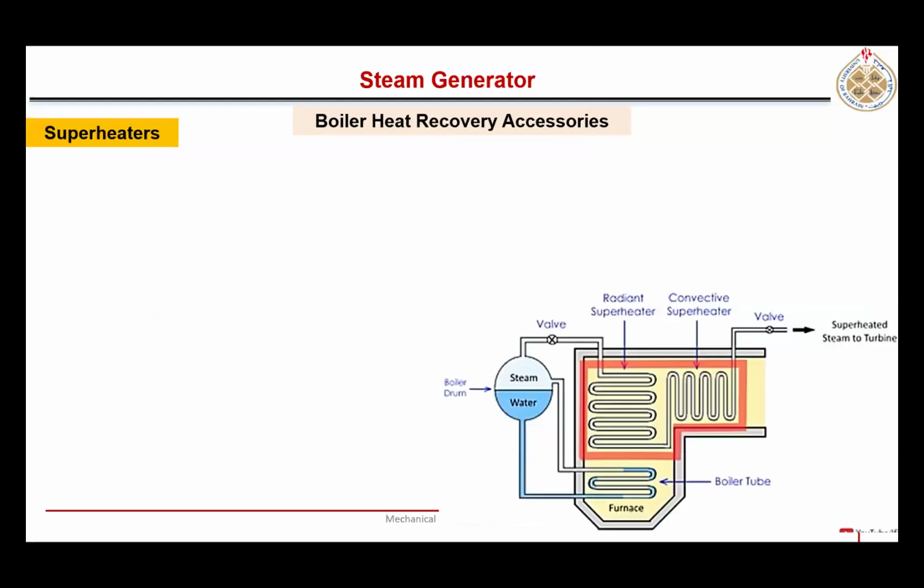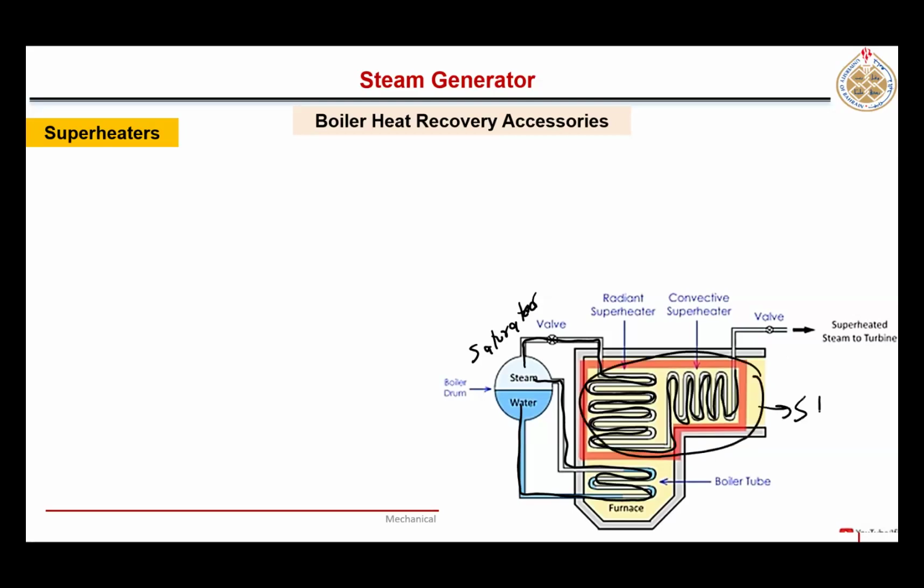Okay, next, superheaters. Superheaters, they are responsible for the following. For example, here the water is converted into steam, but that steam is saturated. To convert it into superheated steam, this steam is again sent to another heat exchanger, this one. So this whole part is actually acting like a superheater. From the same furnace, those hot gases are flowing over these tubes, which are acting like a superheater.